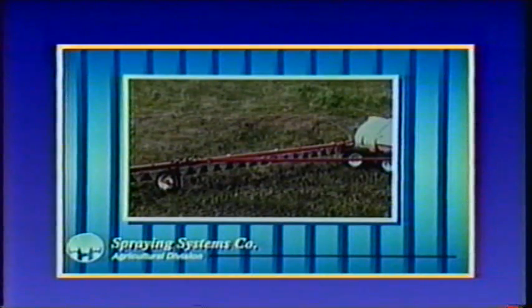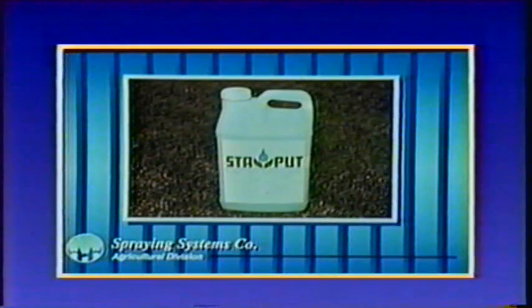Shielded booms have been gaining popularity as environmental concern has heightened. These protect the spray pattern from the wind and allow the spray droplets to reach the target with minimal disruption. Shields are available for individual nozzles or entire booms. Drift control additives or thickening agents can reduce downwind drift by 50 to 80%. There are a number of products available as additives, and it's important to follow label directions carefully. Incorrect concentrations or mixing procedures can lead to poor distribution patterns and low flow rates.